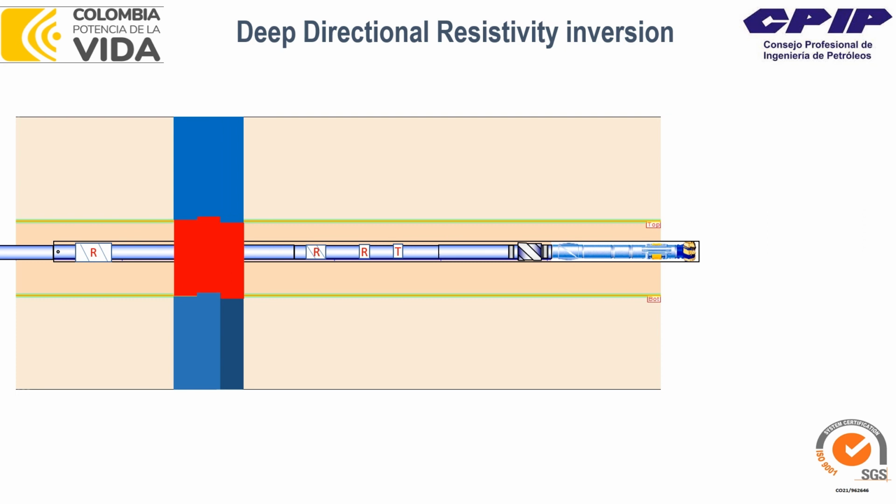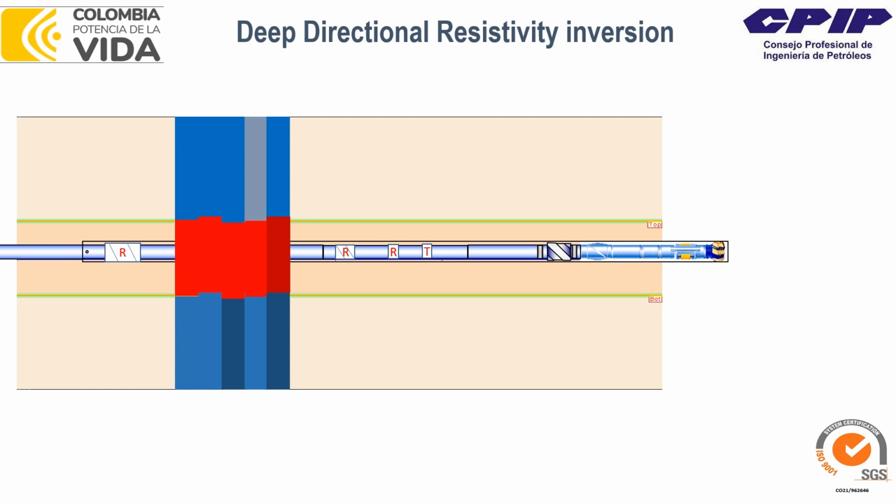And we drill more, and you can see it can be slightly different because, as I told you, this resistivity can be not 4 ohm-meters anymore, not 2 ohm-meters, it can be 1.5 or something, because each iteration to calculate the result is different here. And we have drilled 1, 2, 3 meters, 4, and 5, and 6, right? So you see little by little, the tool and inversion creates the picture for you. And here you see only 6 meters of calculation.